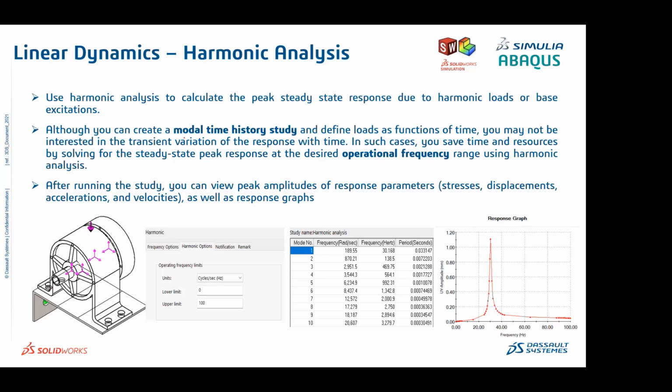Once you perform a frequency analysis, you will understand that, say, my first mode is 30 hertz, my second mode is somewhere around 60 hertz, and my third natural frequency is somewhere around 200 hertz. And you can see your operating frequency, lowest and highest. If your operating frequency is from 0 to 100 hertz, it is very important to see what stresses are developed at this 30 and 60 hertz, because these frequencies might act as resonating frequencies.